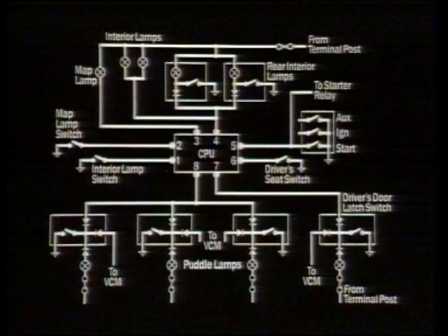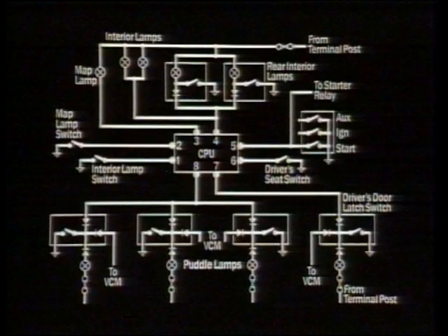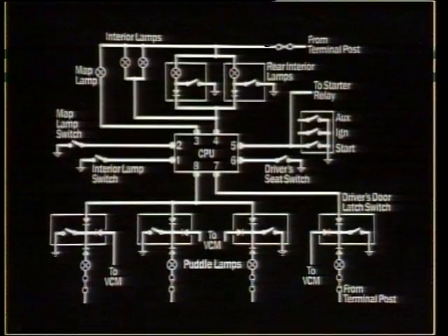If you have to diagnose any faults in this circuit, on no account use a test lamp. Always use the Jaguar diagnostic system, which is featured in a later section of this disc.